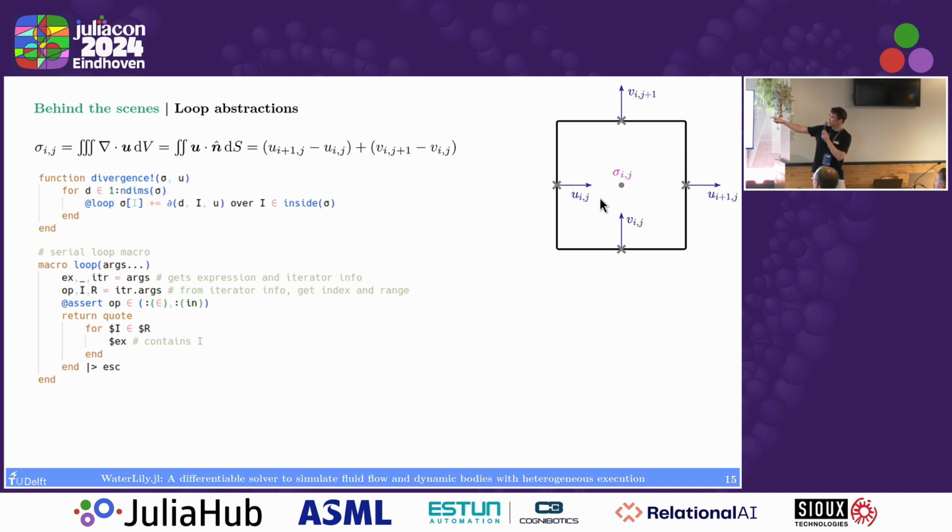Well, I haven't mentioned, but here for this divergence operator, we have a couple of helper functions. This partial delta just says, when I am in this Cartesian index, I look at the direction small capital I, and then go one step behind and one forward and see the difference. And we do this for the different dimensions of the problem. So you can see here also that this is multidimensional because we operate with Cartesian indices. So writing a 2D flow solver or a 3D flow solver is the same. We don't modify our algorithms.